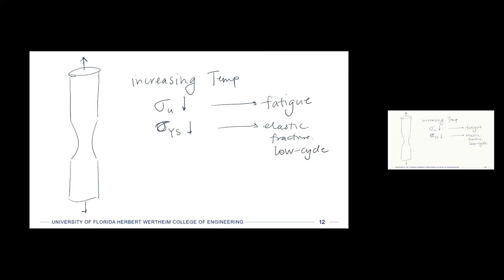Because low cycle fatigue assumes that at some point, if the stress is low enough, we'll have mostly elastic deformation. At the same time, the sample is elongating, right? So we're building up really high strains. And because of these other things that are happening, stress concentrations usually are not as high, because everything is having a little bit of relaxation locally. So you have stress concentrations going down.